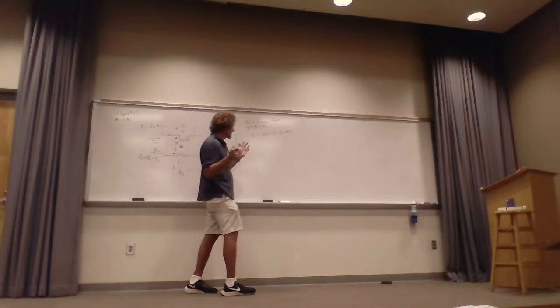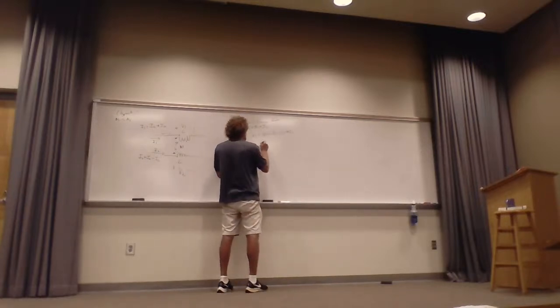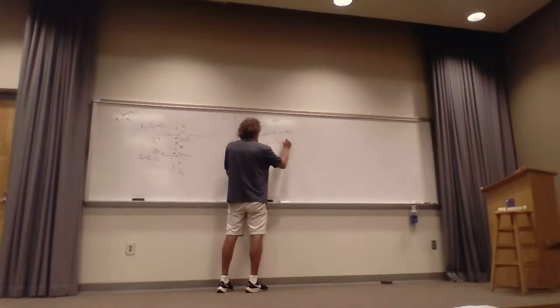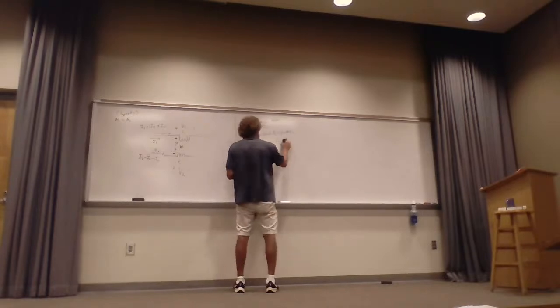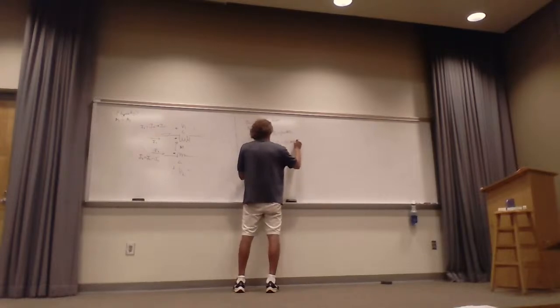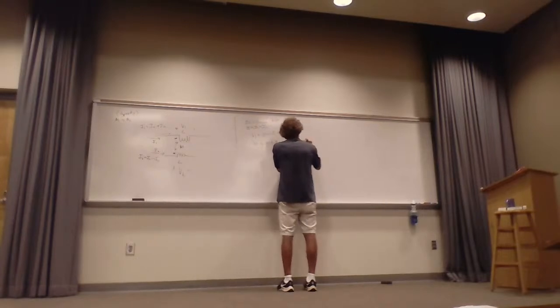All right, I want to get V1. Now that means V1 is equal to j omega L I common plus j omega M I common, or it's simply j omega times L plus M, times I common.